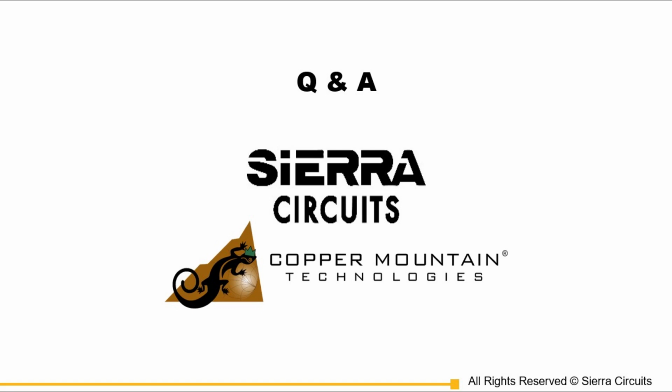So my question down to you on the same thing: when you have a coplanar kind of structure, to make that coplanar ground on both sides very, very wide also may not be a good idea many times. What do you have a feeling on that? Oh, to make them wide, you say? No, less wide. Oh, yes. Because otherwise, if you make it very, very wide, then you will have to stitch another row of stitching vias and all that stuff.